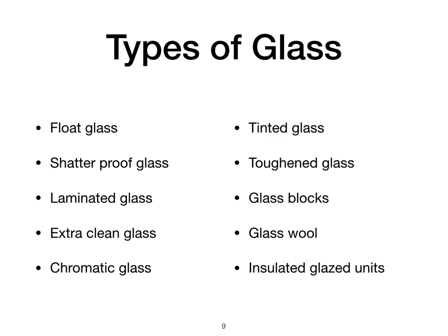Insulated glazed glass units contain glass which is separated into two or three layers of air or vacuum. They cannot allow heat through because of the air between the layers and act as good insulators. They are also called double glazed units.